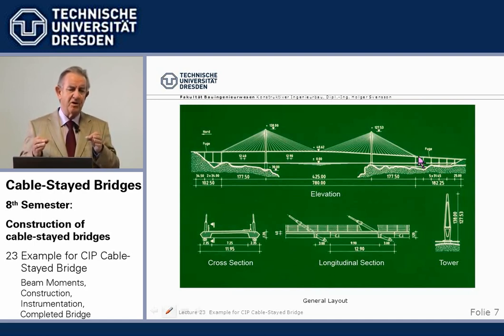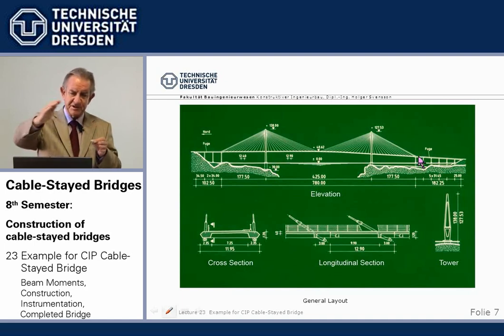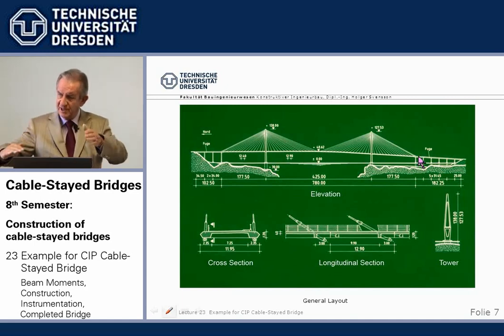is dangerous for wind transversely because of the reattachment of the vortices. It's too short. The vortices don't reattach and damp the thing. So very, very slender dimensions both ways.